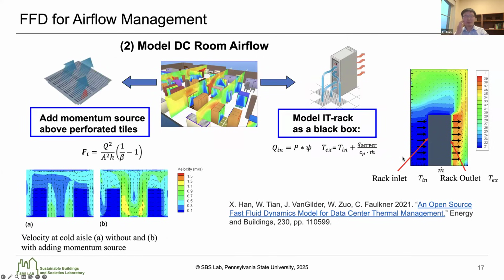So basically we compile the C code as a dynamic link library, and then during the simulation, the Modelica model can communicate with the CFD, the C code. So even though it's within Modelica, it's not directly programmed with Modelica. So actually, it's a separate CFD model. Yes, it is a coupled simulation.